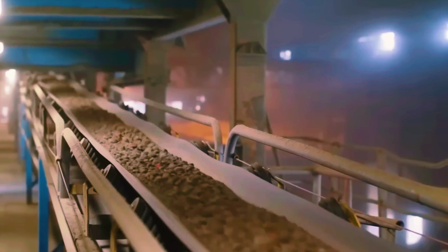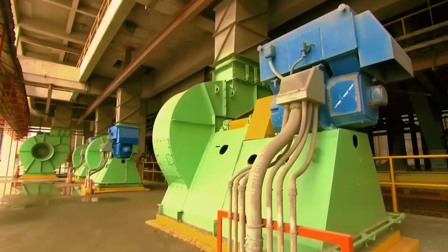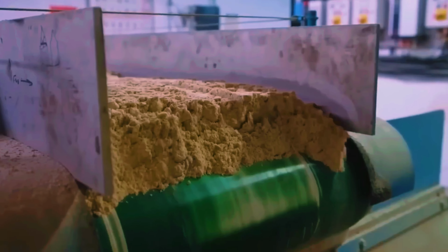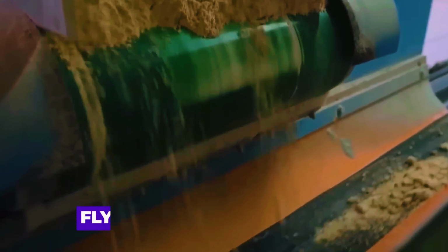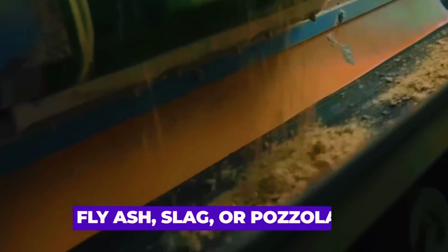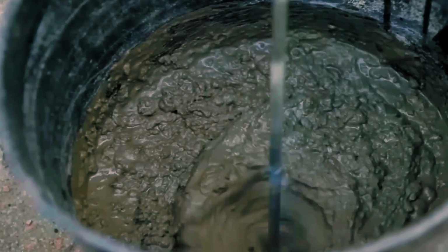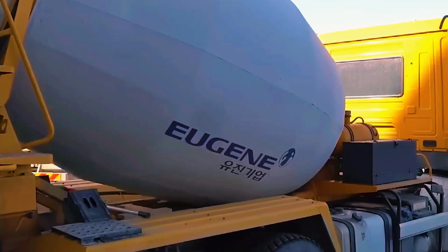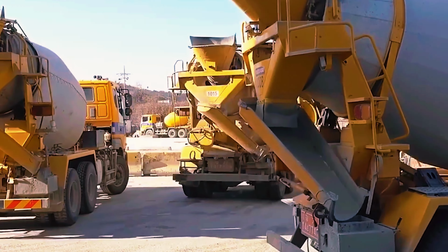The clinker is discharged from the kiln and passes through a clinker cooler where air is blown through it to reduce its temperature. Cooling the clinker is important to maintain its quality and prevent the formation of undesirable crystal formations. The cool clinker is then ground with gypsum and other additives such as fly ash, slag, or pozzolana in cement mills to produce a fine powder. Gypsum is added to control the setting time of the cement. Once prepared, the cement is ready for transport to the concrete factory.